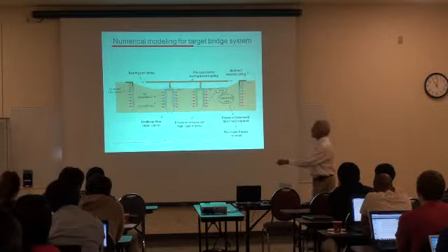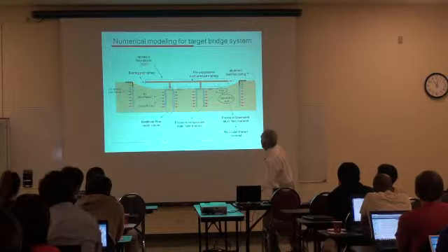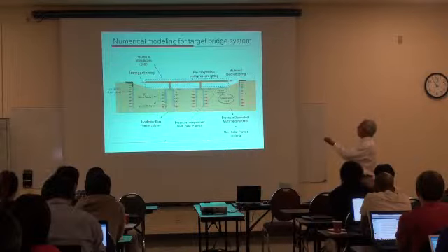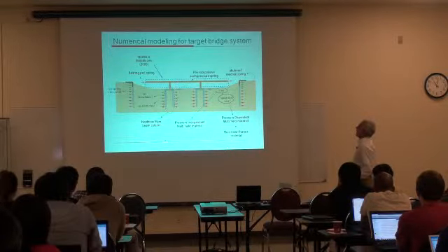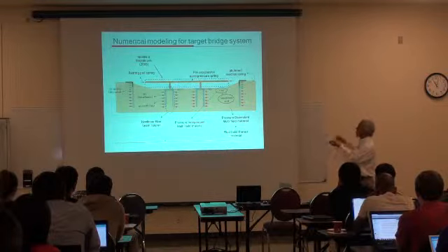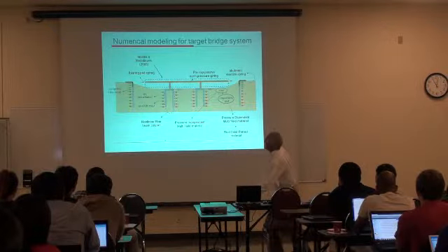Then we use nonlinear fiber beam columns in order to represent the pile foundations. And we use, that's a good thing, a model of the bridge that had been developed by Mackie and Stojadinovic in 2003. So they have put a lot of time in developing the bridge. And we could connect that with our soil.